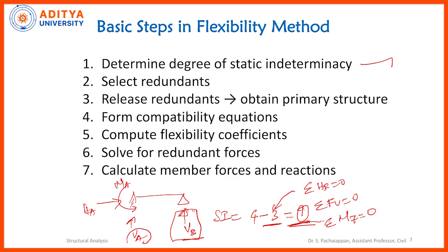Then we need to release the redundant force and obtain the primary structure, and we need to form the compatibility equation and also compute the flexibility coefficients. So, when we are solving the problem, we are going to see how to calculate the flexibility coefficients and all these things. But this lecture is just an introduction. And then we should solve for the redundant forces and finally calculate the member forces and reaction forces.